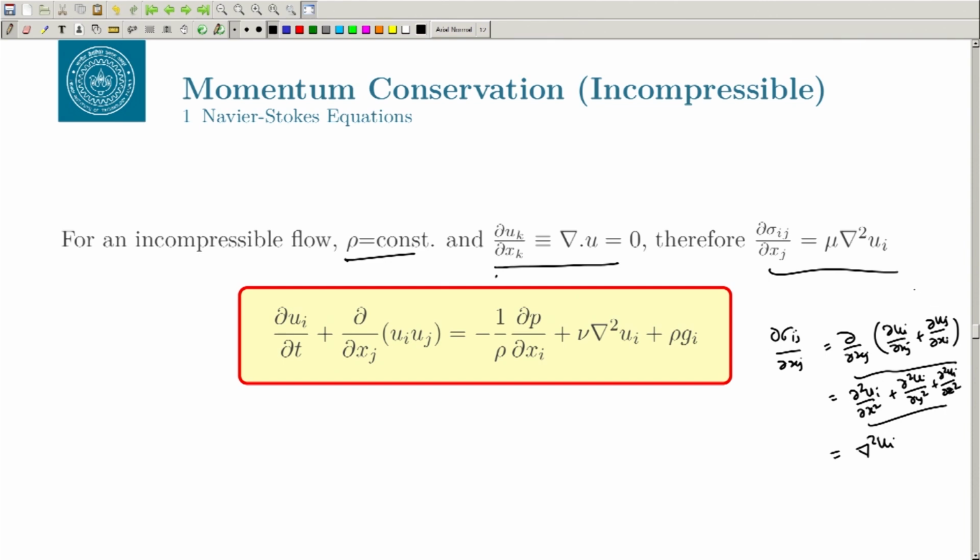And recall that you need to make sure that del dot u goes to 0 when you are deriving this. Okay. So, those components will cancel out, and this is the expression that you get, and this becomes even simpler for the incompressible flow. There is no second coefficient of viscosity, and that is why the term minus 2 by 3 delta ij E kk goes to 0. Okay. And it becomes very, very simple, it is a Laplacian term.